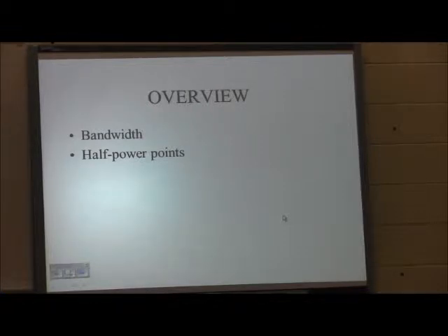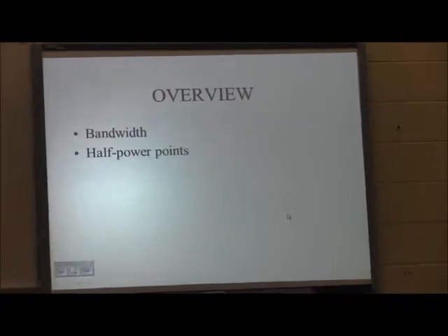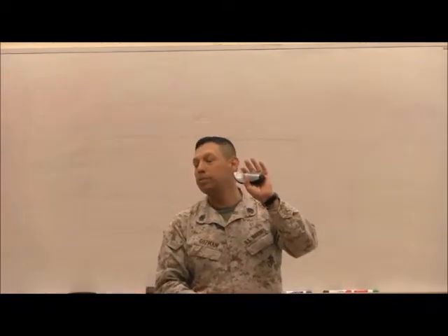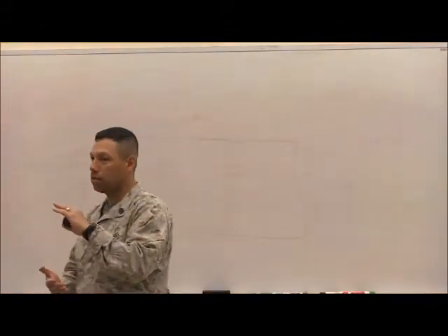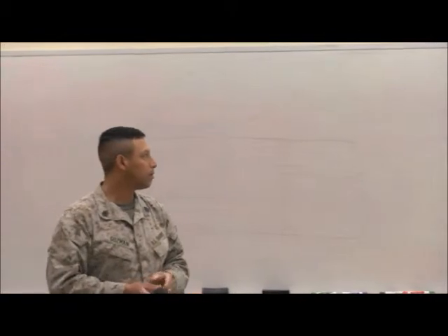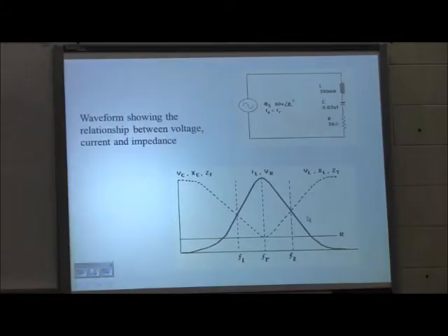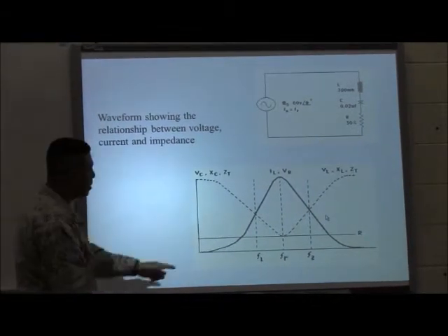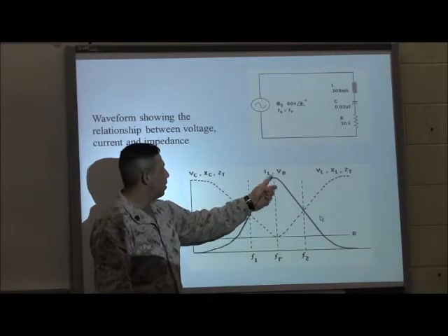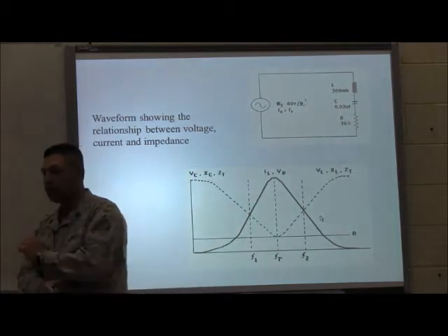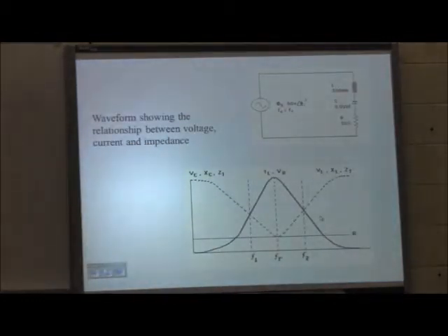In series, at resonance, the only opposition felt in the circuit is what? The resistor. So is total impedance at its max or at its minimum? It's at its minimum. So total current is at its max. Impedance here equals resistance, and total current is max.